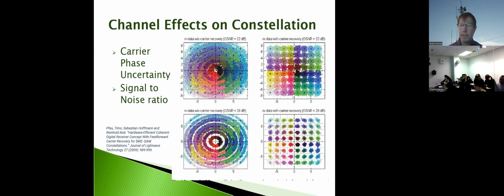And so when that gets to the receiver, there might be some arbitrary phase that has been added to this constellation. It'll cause a rotation, right? Remember, we're looking at this in a complex plane. If instead of looking at it in Cartesian coordinates, we look at it in a phasor or polar coordinate situation, then we realize that the rotation about the origin is directly sensitive to the phase of the signal.